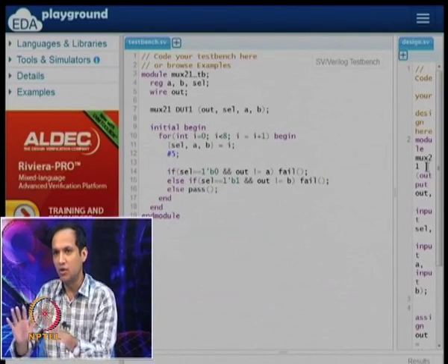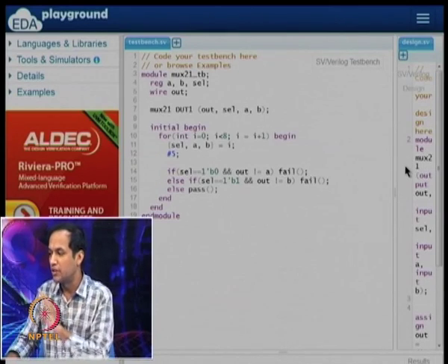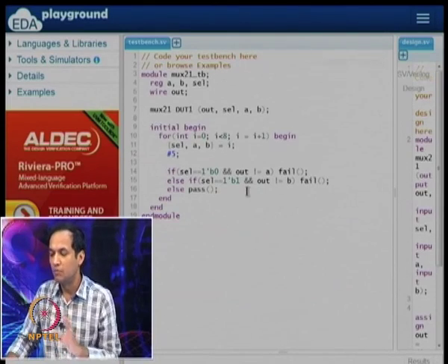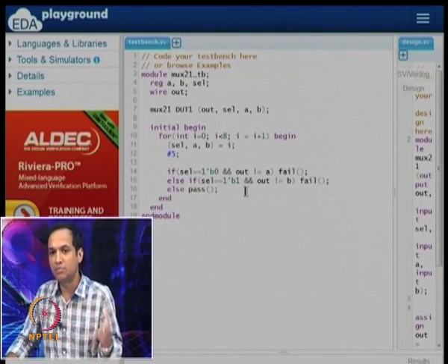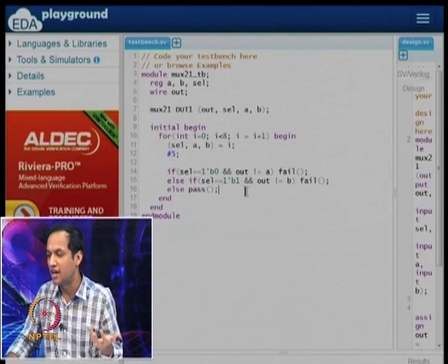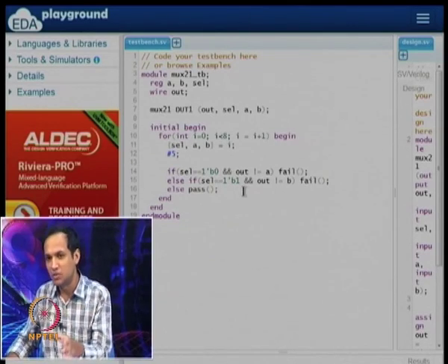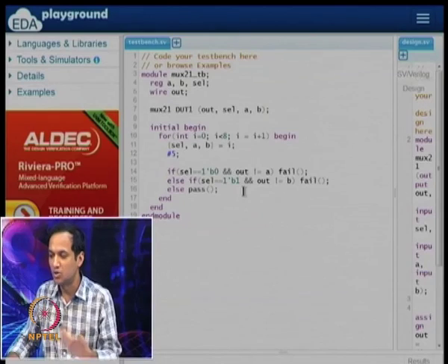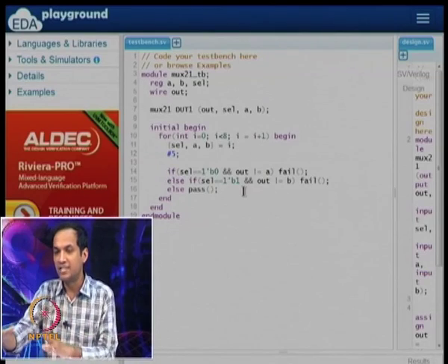In the test bench we are going to use the full power of writing software, as though you do it in a programming language. When you write the design description, you generally do not write functions and so on, but when you are testing it, your test bench is essentially a piece of software by itself. It is not implying any hardware directly. It is not that we want to synthesize an oscilloscope or get a voltage supply out of this. If we give this voltage supply and we have to see the waveforms, what is going to happen? That is what we are doing in this whole business of simulation, right. So you can use the whole power of software programming inside the test bench.